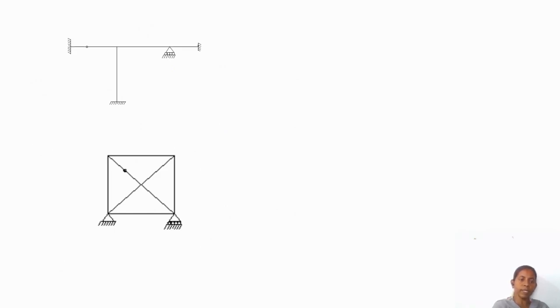So in this an internal hinge is present, so 1 release is possible. Here it is a roller condition. So here 3 number of unknowns should be counted. Here 3, here 3. So all the known parameters should be mentioned so that it will be easy for the next step.